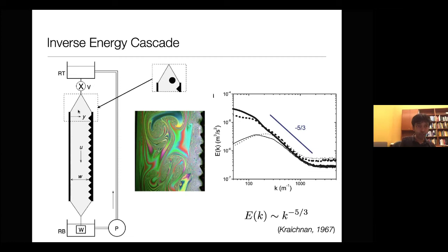So if I don't introduce a comb at the top, and I simply have this rough wall, as you can see from these images, it is going to create very small scale turbulence around those rough walls. And that turbulence is going to slowly diffuse out. But to hasten the diffusion, because otherwise you're going to need a very long channel, what we do is we stick a very big rod, again perpendicular to the plane of the film.